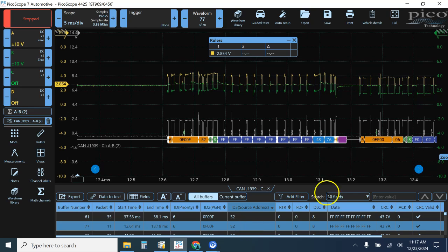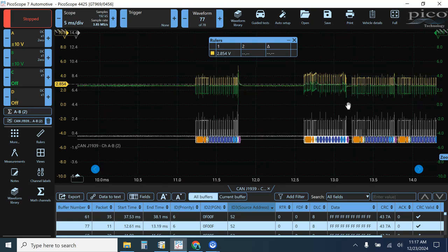So in this case, I would have a knock sensor more than likely with 10 ohms of resistance in it. It's enough for the electronics in the device to power up, but as soon as it would turn the heater on inside the knock sensor, which is going to draw a few amps, it's going to fall on its face. The device is probably going to reset. It'll come off and it would be on and off of the CAN bus, and I'd have some DTC related to missing knock sensor or even something about knock sensor invalid. So anyways, this is the same failure mode. You've seen it. It depends on the device and it depends on the amplitude of how much resistance I have in the ground, but it's the same kind of thing.